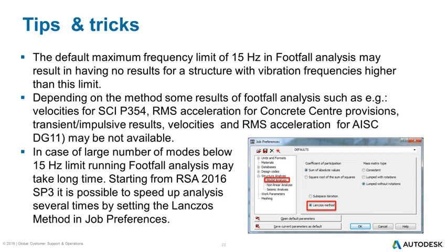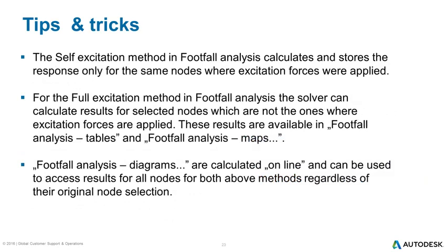Also mind that for the selected code, some types of results are not available, as you could have seen for my slab model. That was for velocity. In case you need to see the response in a different location than where the excitation happens, you have to use the full excitation method. But as I mentioned, the full excitation requires more time to complete calculations than the self-excitation method, so use it only when you really need to have these results.